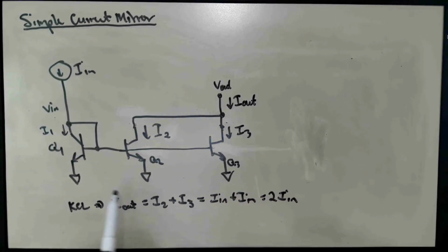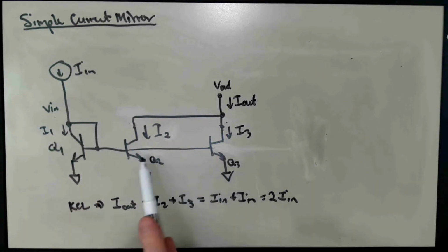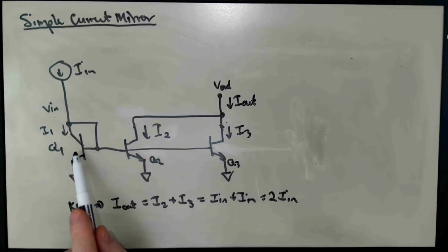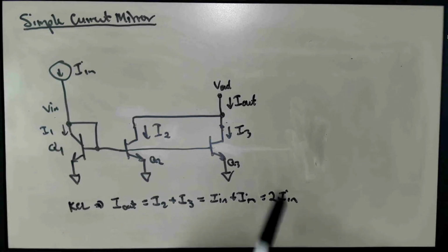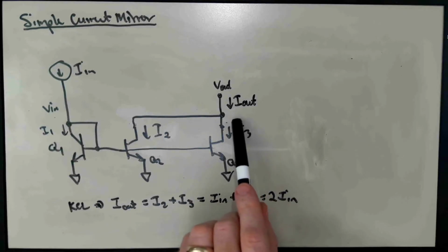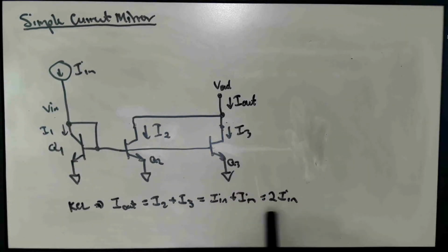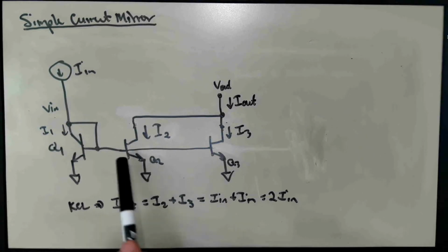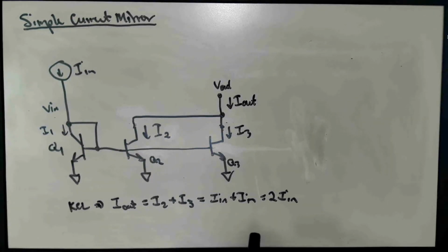So we have the ability to take an input current and to double it by just having 2 matched transistors on the output side connected together in parallel against 1 on the input side. We could take our third one and connect all 3 outputs together and wind up with a current amplifier that amplifies by a factor of 3. If we were to put 2 transistors over here, it turns out we could actually attenuate a current by a particular factor.